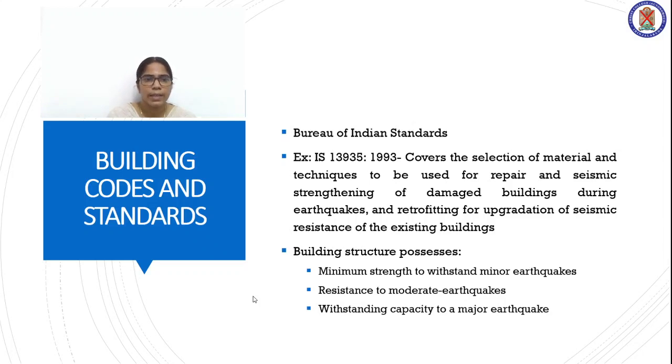An example of a BIS standard is IS 13935:1993, which covers the selection of material and techniques to be used for repair and seismic strengthening of a building damaged during an earthquake, and retrofitting for upgradation of seismic resistance of existing buildings.